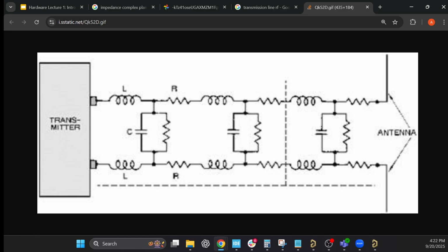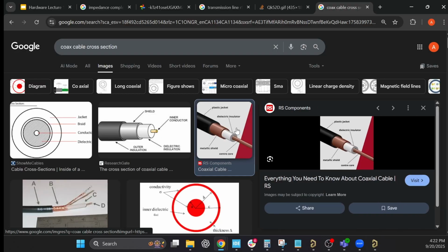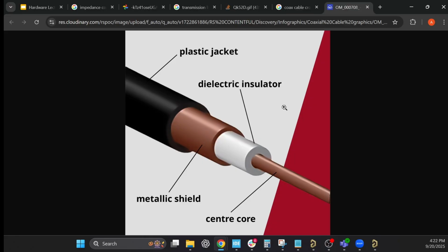They specifically designed it so. There are a lot of factors that affect coax cable: whatever the insulation is, the diameter of the metallic shield, and the diameter of the internal wire. Changing those ratios will get you different impedances, and your per-element inductor, capacitor, and resistor values will be different.